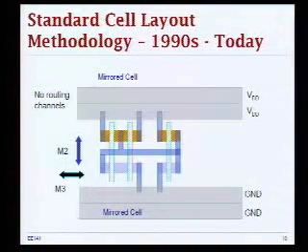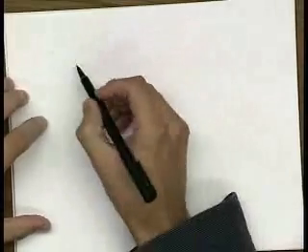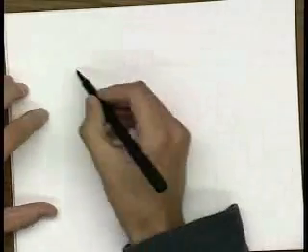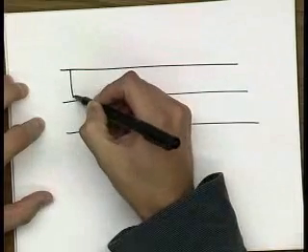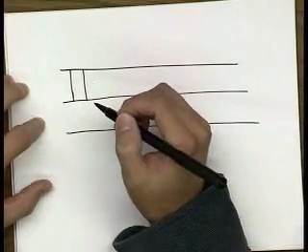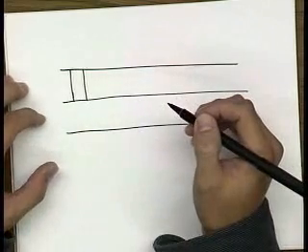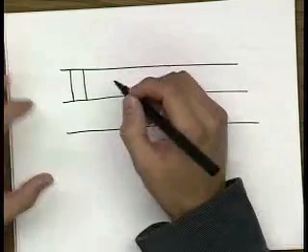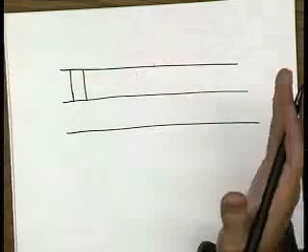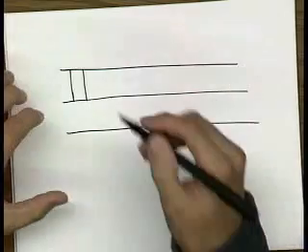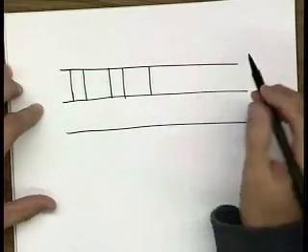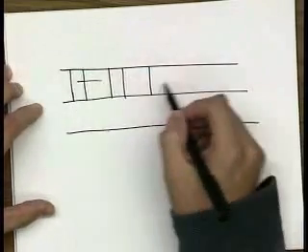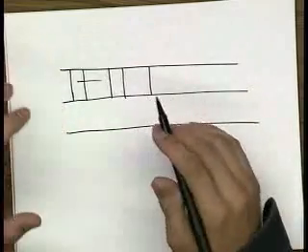And what that gives you is, if you go to the overhead camera for a second, the way you would implement your function is, if I know that my standard cells are all the same height, I would just create rows of standard cells, and then I would put them right next to each other. So this is, for example, my inverter. If I need to implement a little bit more complex gates like NANDs and NORs, then I would need to put more transistors in, and my standard cells will be a little bit wider, but they will still be the same height. You just keep the same height, and this would be, for example, a NAND, another inverter, and so on. And then you just connect all these cells using the routing at the top level, routing methodology.